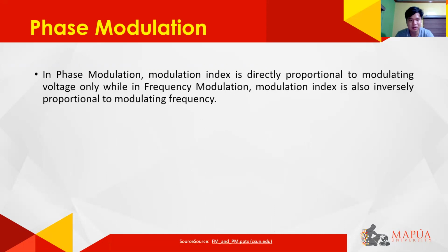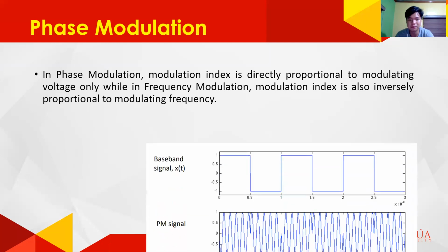Next. In phase modulation, the modulation index is directly proportional to the modulating voltage only, while in frequency modulation, the modulation index is also inversely proportional to the modulating frequency. This is a very important concept for us to remember.